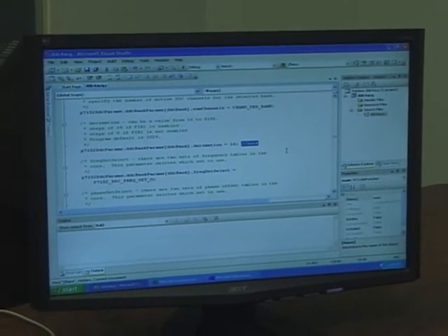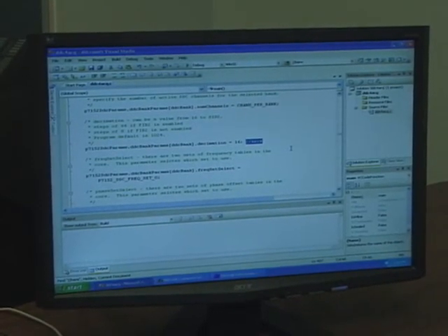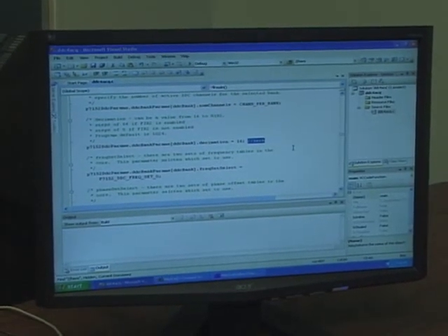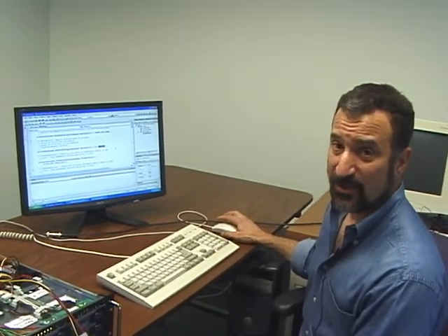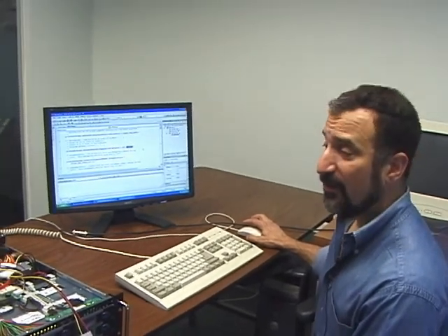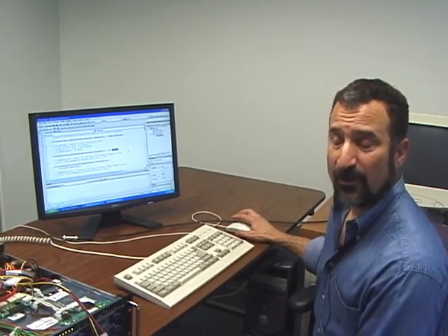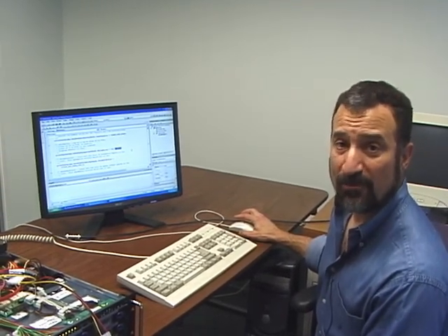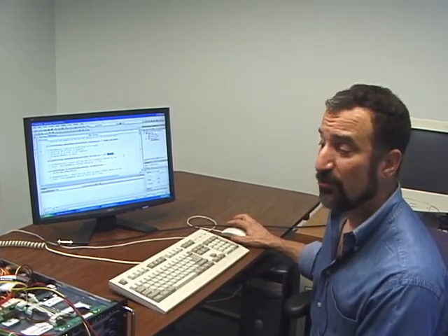Since I have 4 DDC channels, each giving me 12.5 million complex samples, and a complex sample is comprised of 16-bit I and 16-bit Q, each DDC is providing us with 50 megabytes per second of data. Therefore, in this example, we will transfer 200 megabytes per second of data across the PC backplane into the PC's memory.